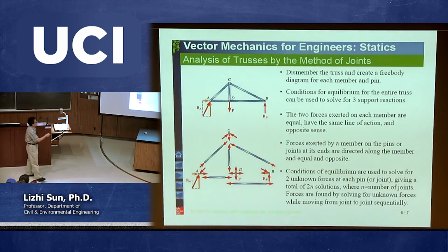At each point, we can establish 2 equations. You may say, why not 3? Well, when we talk about the free body diagram for each point or each particle, there are only 2 equations. The third equation, which is a moment equation, doesn't work. It becomes a trivial equation because there's no distance involved. You only talk about 1 point. That's chapter 2 stuff. So in chapter 2, when we plot the free body diagram about each point, typically we have 2 equations only.